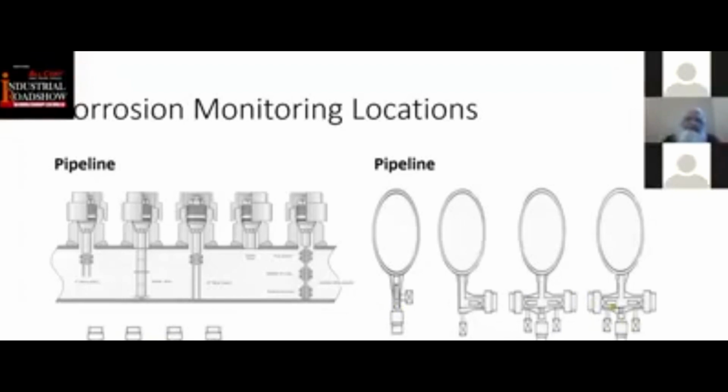All these mounting devices are either installed at the construction stage, and they are recommended at the FEED and design stage. But if they need to be installed while the system is on, then they are to be installed through hot tapping, because nobody would like to shut down the processes just to install the corrosion monitoring devices. The hot tapping is very successful and a technically very useful technique to install the corrosion monitoring devices without shutting down the system.